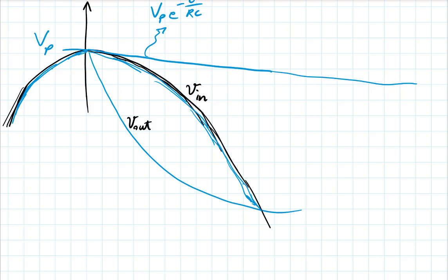And there's no way for the current to go back through the diode in reverse. So the capacitor is actually still discharging in the resistor, but just not as fast as it would have had it been sitting alone together with the resistor only, right? It means that the capacitor and resistor combination have a response time that's fast enough so that they can still follow the variations on the input.